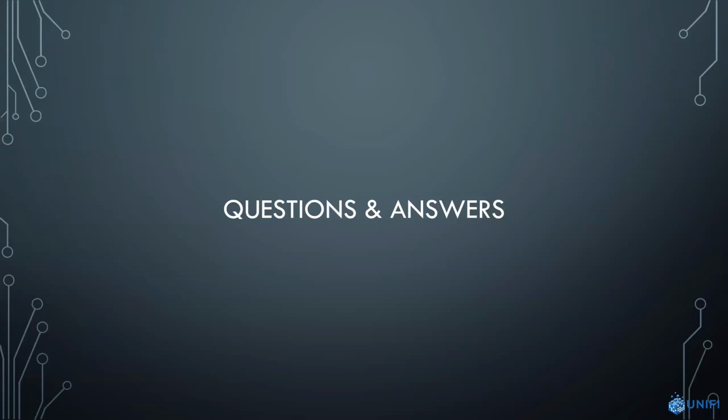Yes. So the BIM coordination with an emphasis on data. Earlier I mentioned a lot of times when you hear the term BIM coordination, people are referring to spatial coordination. So looking for clashes, for constructability issues and things of that nature. But part of what I'd like to propose here today to all of our engineers specifically on the line is how can you actually start to use the data within your models to coordinate other users' data. So other team members, maybe it's another discipline. Again, going back to that example, let's take a piece of mechanical equipment that we'll need to tap into, and we'll need an electrical connection. How can those two trades really use BIM to its fullest potential? Really that's to get on the same data set and coordinate in terms of data using the parameters within your model.